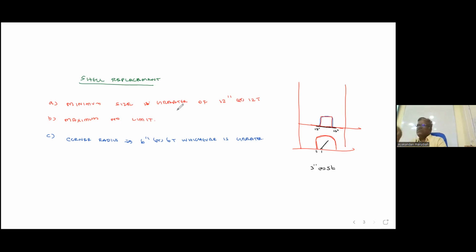When you are welding a replacement along a horizontal joint, we have to cut the horizontal weld 12 inch on both sides, then weld it last. If we are making the replacement at the shell to bottom, it should be a tombstone shape. And the distance to any annular plate weld should be minimum 3 inch or 5T, whichever is greater. These are the key points.